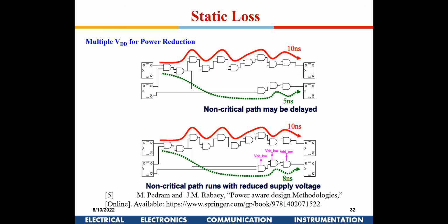So these are the kind of things which are actually employed in processors. In these designs, although this is targeting static power only, to reduce it, we initially think it is in picoamperes, so we don't have to worry. But you also have to think in terms of the number of transistors. There are billions of transistors, right? So this picoamperes times a few thousands will also take it into nanoamperes. That is the reason you have to take care of these issues also. So this is one way of doing it.